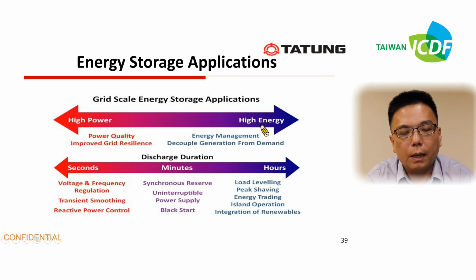We want to separate and understand its application. We can understand from its discharge duration: seconds, minutes, and hours. If you use the energy storage on the second scale, you can do voltage and frequency regulation, transmission smoothing, and reactive power control.